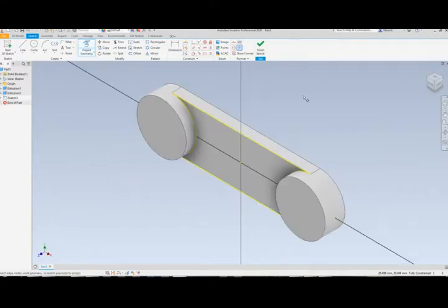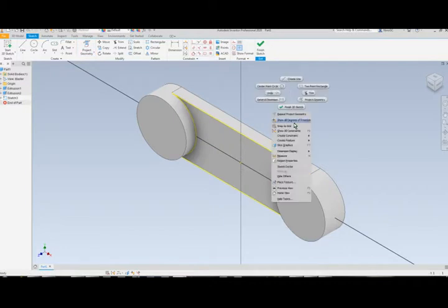My first additional tip is that if you go right mouse button, about a quarter of the way down, there is Slice Graphics, and on the flyout right next to it, it shows F7. If you hit F7, it will do the same thing that Slice Graphics does.